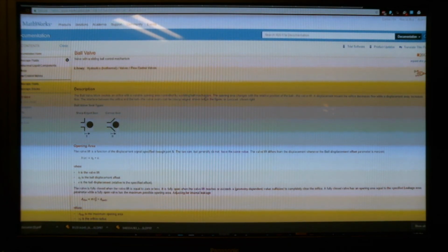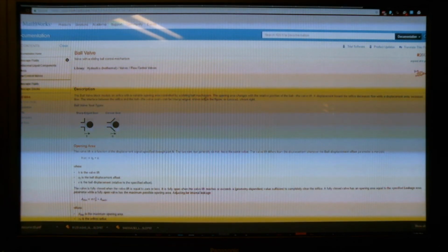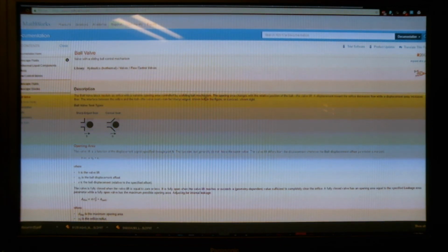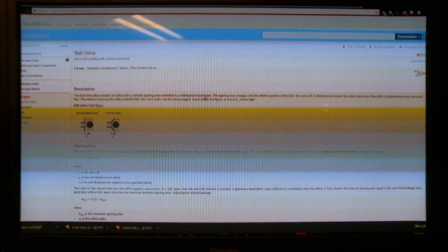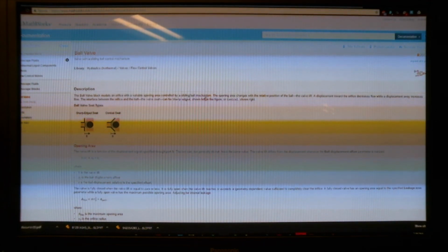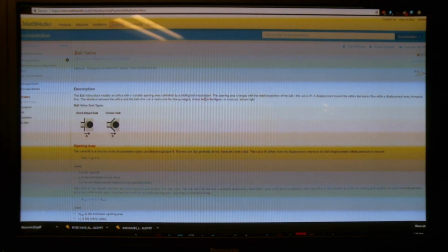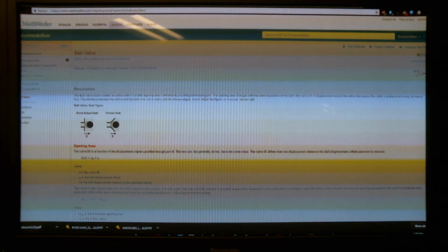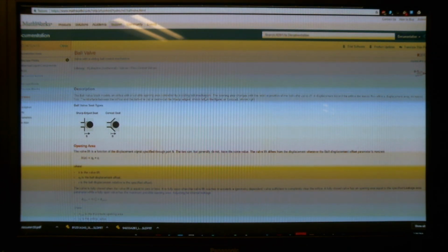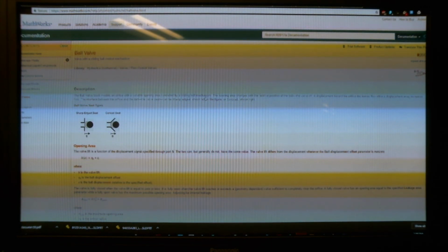Very cool. Yeah. Because I saw that they wanted effectively discharge coefficient, flow area, and whatnot. Yep. It'll take a lot of information sometimes, but then there's also simplified models of mostly everything. Like the gearbox doesn't account for inertia. So what you do is you can add inertia to the output of your gearbox related to what your gearbox inertia should be. And that's effectively just your standard gearbox inertia calculation. And then you can model that as well as other stuff.